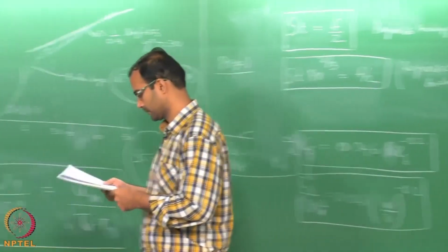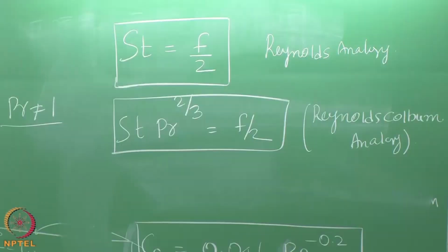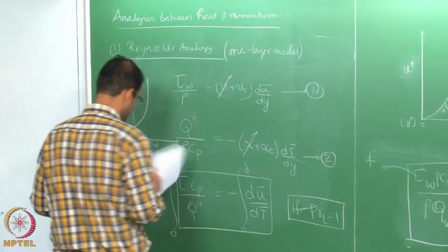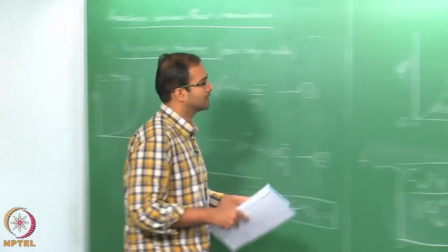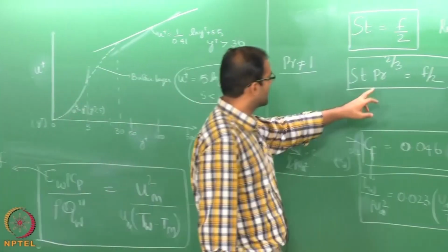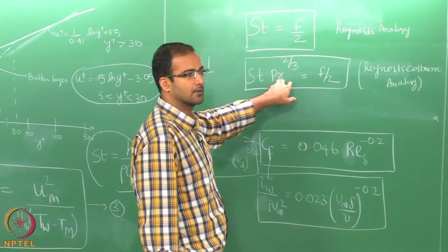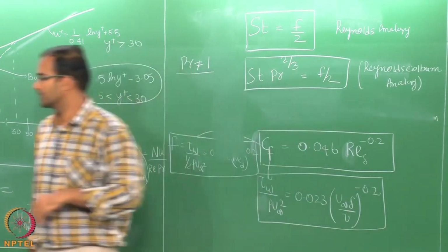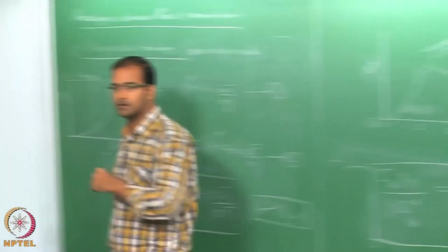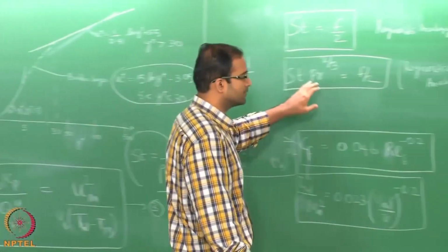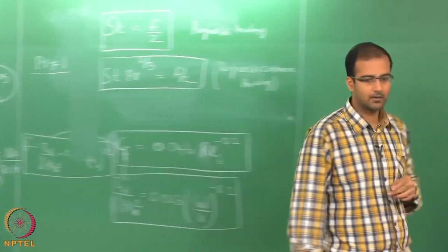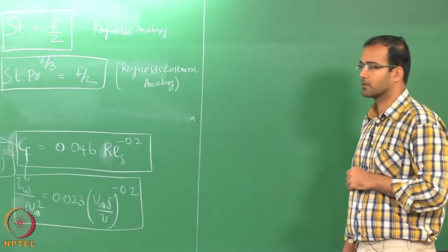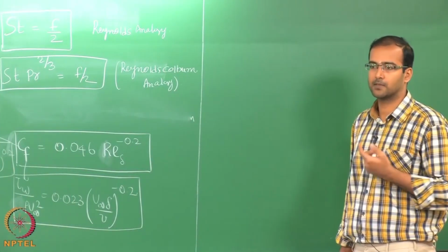Okay. So, the effect of the molecular Prandtl number is also brought into this. Okay. This is not turbulent Prandtl number, this is molecular Prandtl number. The effect of molecular Prandtl number, which we have neglected here, has also been brought in later by Colburn and extended to different values of molecular Prandtl number, because at the wall finally molecular Prandtl number is important.